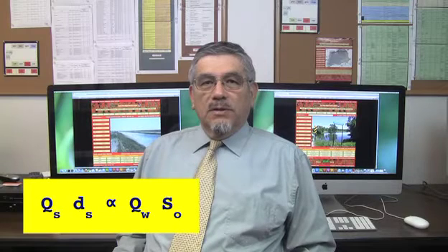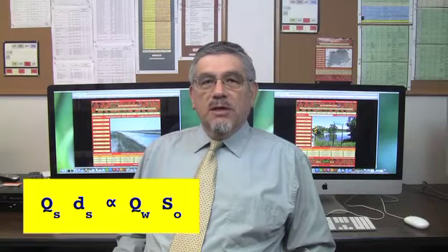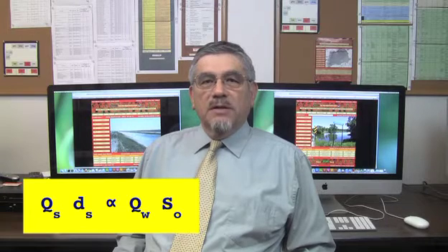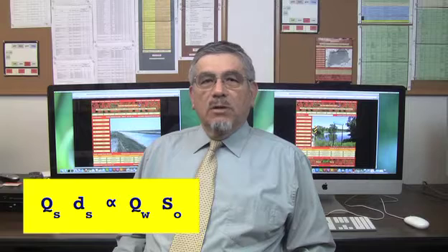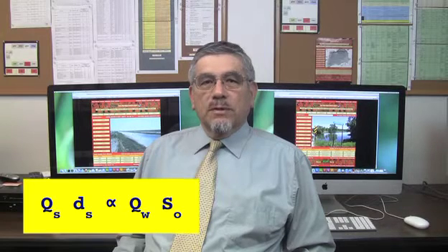In 1955, Emory W. Lane presented a relation between sediment load and hydraulic variables. This relation states the proportionality between the product of sediment discharge and particle size on the left-hand side and the product of water discharge and bottom slope on the right-hand side. At equilibrium, this relation holds.